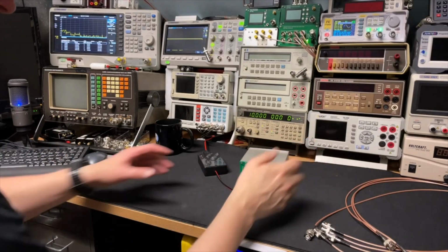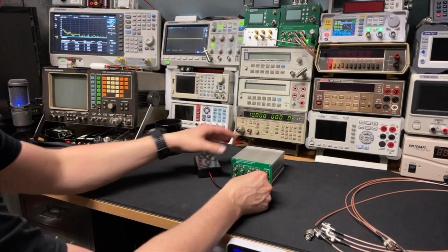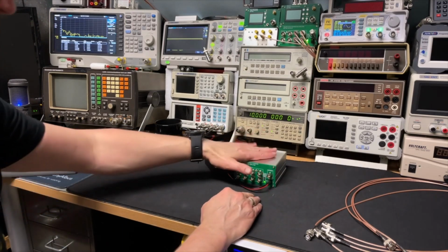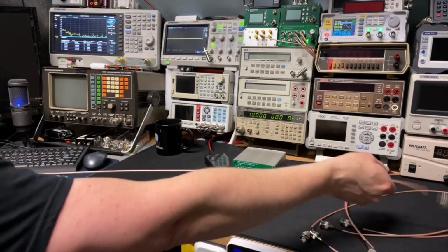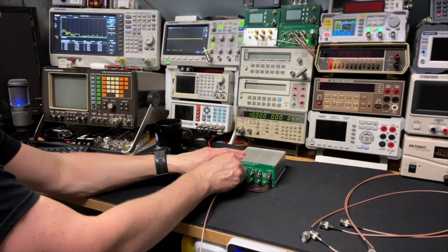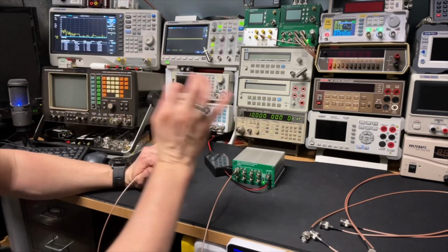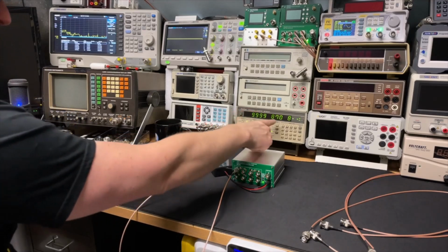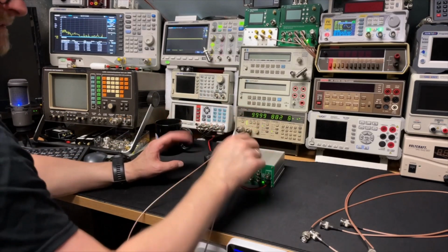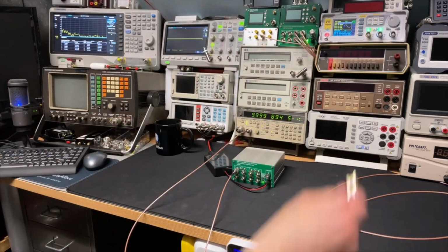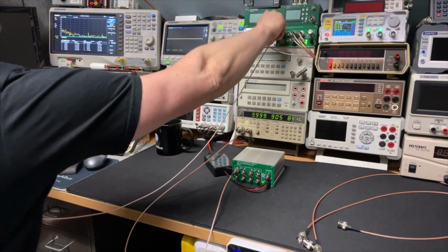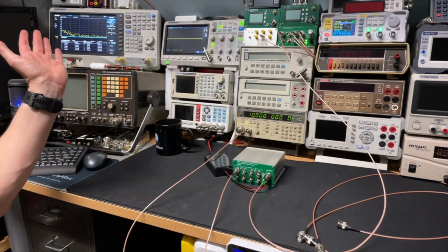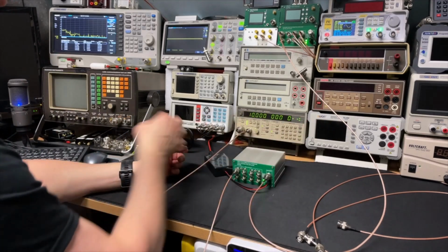Okay, removed everything. I have here now the 10 megahertz distribution. You saw the alarm is immediately off because now it's running on its internal oscillator. And that is maybe fun to see, because it's probably a fraction off, and especially now when it's heating. And as you see, it is indeed a little bit off because it's still heating. But to show you that it will switch its internal oscillator off, I will put something on the input. And then you see it is using it. And now it's exactly 10.